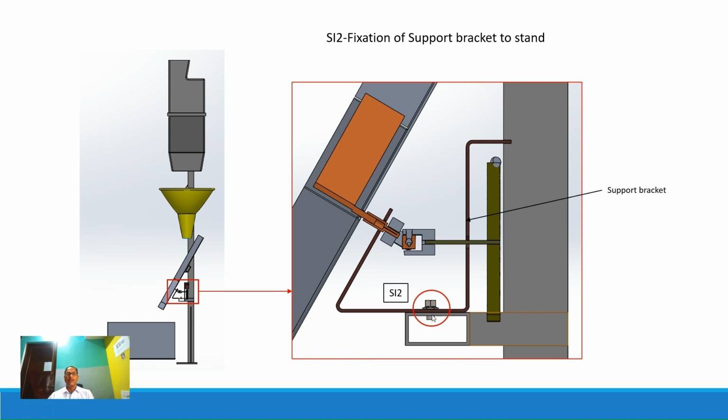Okay. The next one is the fixation of the yoke sleeve to the gate. Okay, initially in the concept phase, this was a single piece. Now it is separated and it forms another secondary interface. Derivation of the design specifications. This is a very important step in the preliminary design and development phase. The derivation of the design specifications is done from the functional requirements.